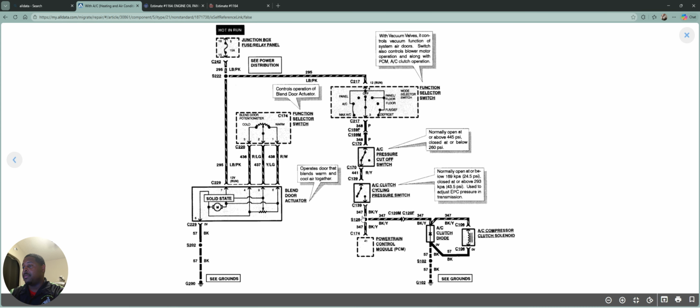That means that no voltage is being wasted here. If it shows 12 volts, then there is a break or extreme resistance or something is not happy in this line. Okay? Since you got 0.014 volts at this location, from what I'm seeing, power is not making it from here to here. Okay?